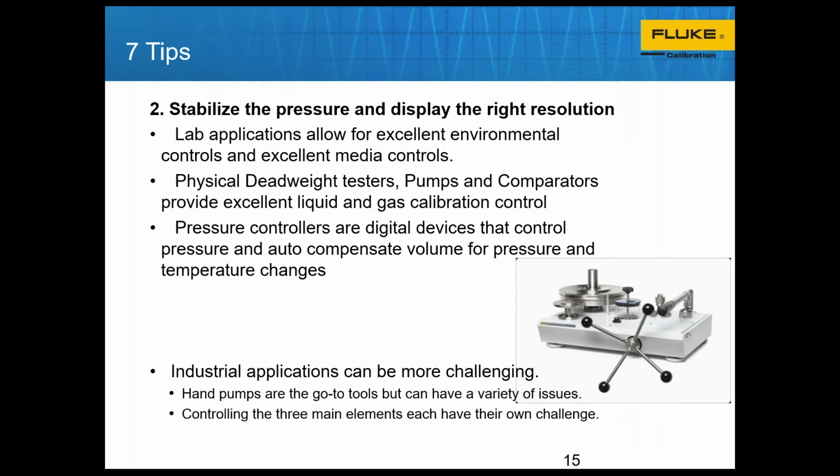There is an option to use lab-based equipment and bring the calibration from the field back into the lab. The lab is a very nice, stable environment from a temperature point of view. It also gives you maybe that extra level of cleanliness that you wouldn't necessarily get out in the field. So if you have an opportunity to bring your pressure calibrations back into a lab and it seems practical, then there's plenty of pieces of equipment out there to help you with that.